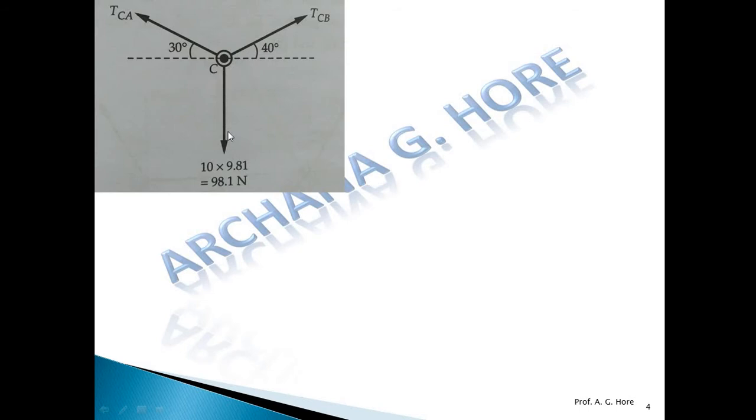under equilibrium. So as per the condition, these 3 forces must be concurrent or parallel. Here directly these forces are given at point C. These forces are concurrent. Now for concurrent forces, we can apply Lami's theorem. For Lami's theorem we want to find out, with all the forces away from the joint, the angle in between these 3 forces.